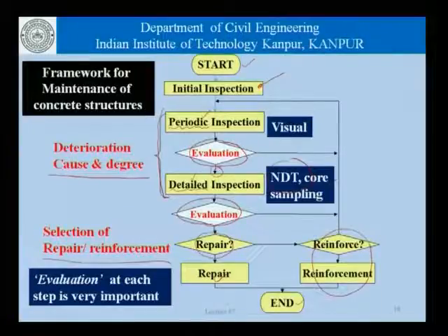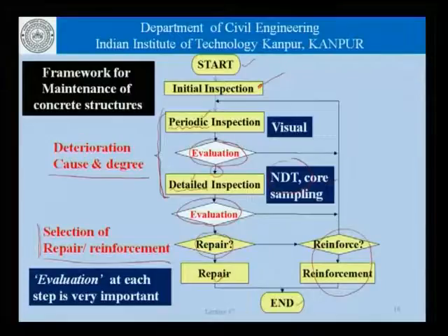As far as the repair and reinforcement of structures is concerned, we need to carry out a survey and find out what is the best method that we can use, what is the most appropriate material that can be used, what kind of equipment needs to be used, and so on. Having said all that, we must remember that evaluation is a very, very important step at the end of each of these processes that we have underlined here. There is an evaluation step at the end of the periodic inspection, there is an evaluation at the end of the detailed inspection, and so on. So, evaluation is basically the process of exercising one's judgment in terms of what is the further action required. All test methods give us certain results, and it requires judgment to decide what is the next step to be taken.